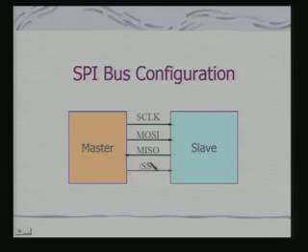This is basically bar, so active low. This is a slave select line. So, using this line you select the slave. In fact, this implies that there is no distinct capability in the SPI bus configuration of associating unique addresses with the devices themselves.